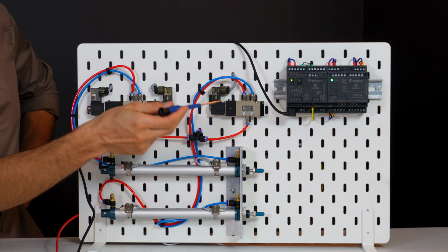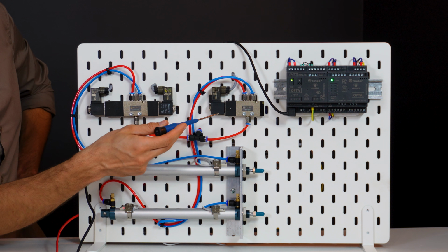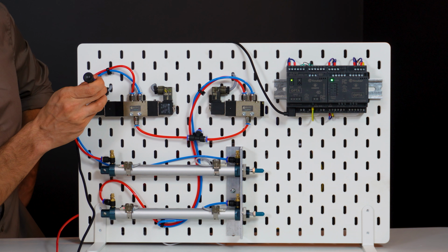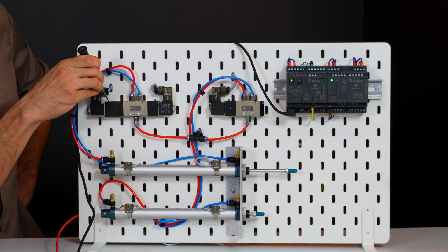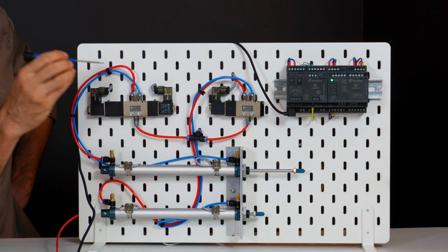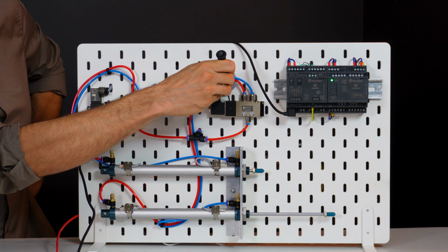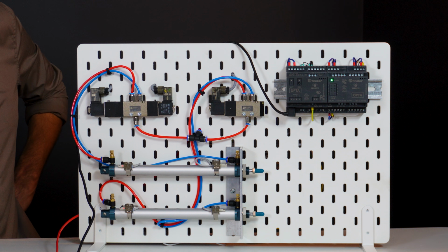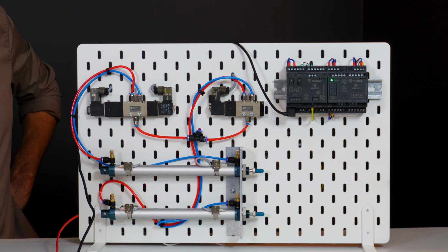As you can see, the logic of operation when controlling these distributors is slightly different. Here, after triggering the operation, we can stop in an intermediate position. For the actuator with the 2-position distributor, however, removing power from the coil means returning to the base position.